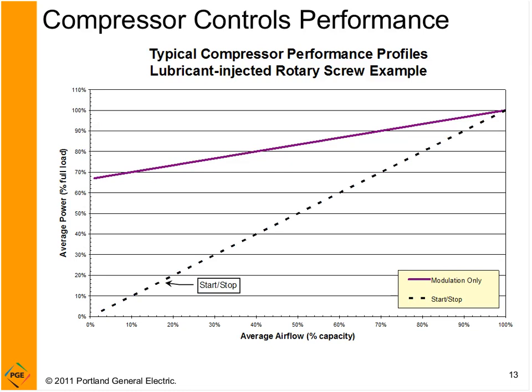Start, stop. We talked about start, stop control, on, off. And on average, just as you might expect, it's simply a one-to-one relationship of flow versus power. So at zero flow, it's off. At 50%, it's going to cycle, start, stop, kind of like a clock. It just goes tick-tock, tick-tock. Half flow is exactly 50% power because it's on half the time and off half the time. Okay?